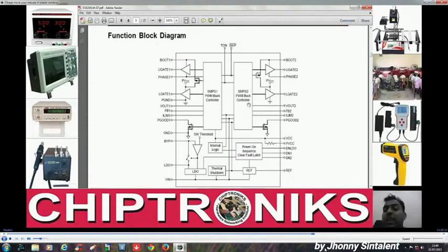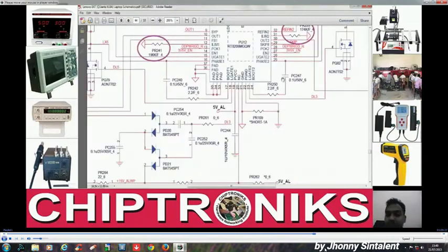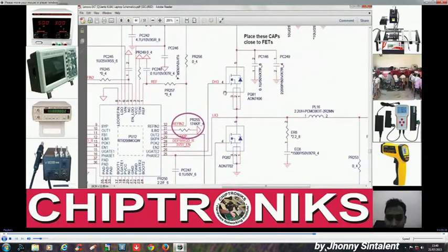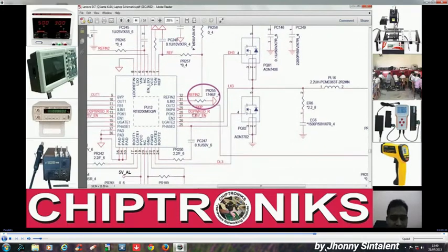So this L gate 2 is generated by the comparator, whose signal is generated by the internal SMPS2 PWM buck controller. Similarly over here, U gate 1, L gate 1, U gate 2, L gate 2. There are two MOSFETs connected over here. You see that two MOSFETs connected, DH3 and LX3.